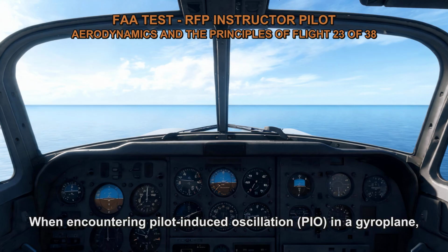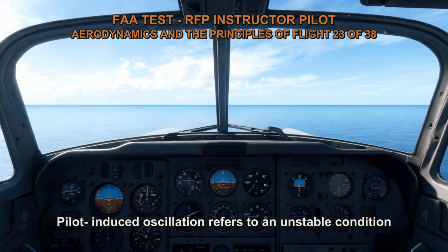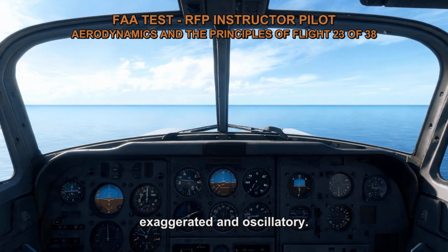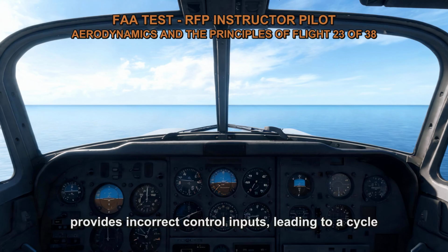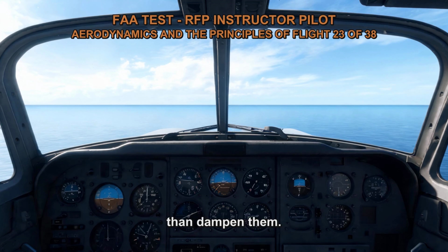When encountering pilot-induced oscillation, PIO, in a gyroplane, the first step in correcting it is to reduce power. Pilot-induced oscillation refers to an unstable condition where the gyroplane's response to control inputs becomes exaggerated and oscillatory. It can occur when the pilot overreacts or provides incorrect control inputs, leading to a cycle of corrective actions that amplify the oscillations rather than dampen them.